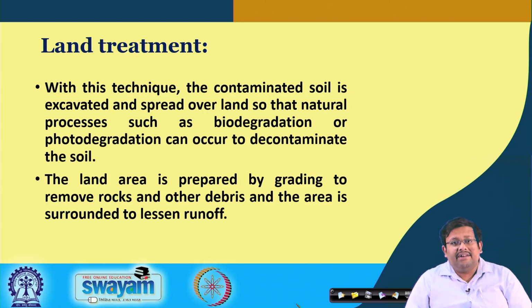Land treatment is a technique where the contaminated soil is excavated and spread over the land, so that natural processes such as biodegradation or photodegradation can occur to decontaminate the soil. So, basically here the soil is excavated and then kept over the surface, so that it can provide the required area for carrying out the bioremediation process as well as other decontamination processes.